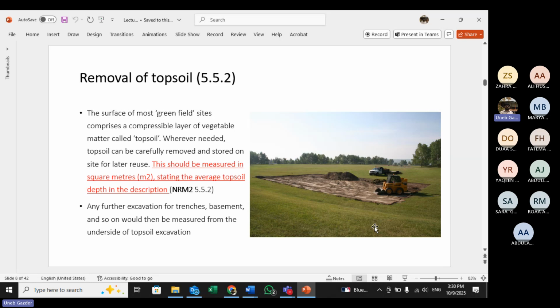We don't want it, because grass means water. The grass will grow as well, and it may have other elements which may interact with the water you are putting in the structure, so it may cause some cracks, and obviously it will hinder and obstruct the construction work as well. So it will be removed. Any soil with vegetation, grass, trees must be removed.